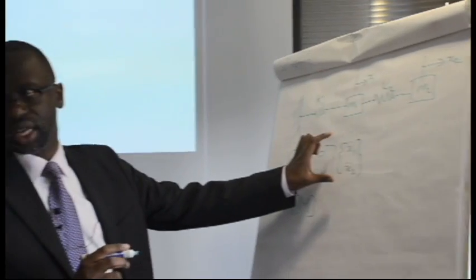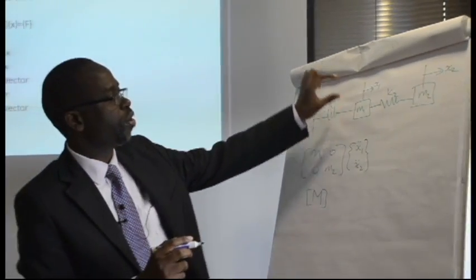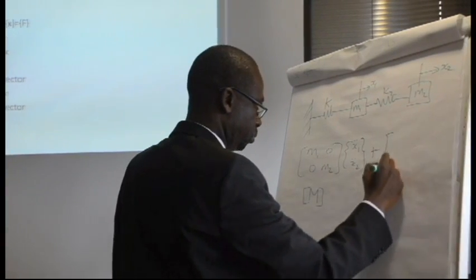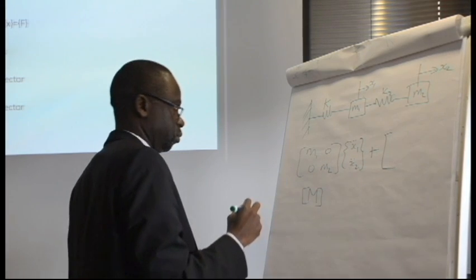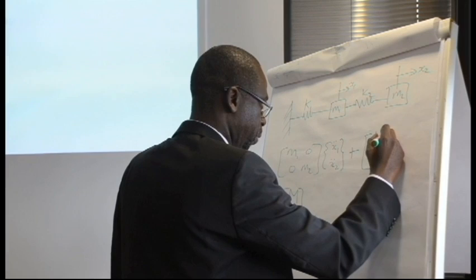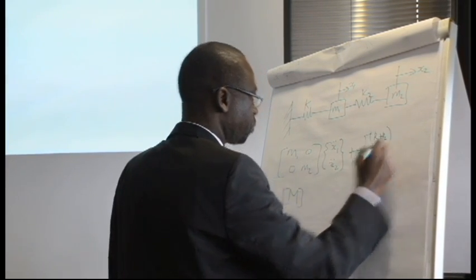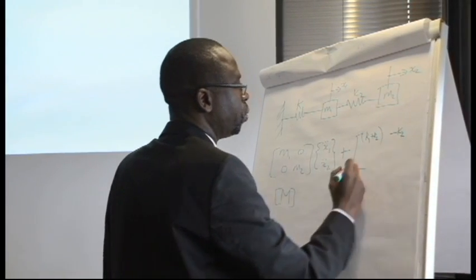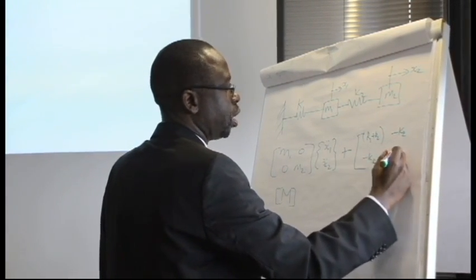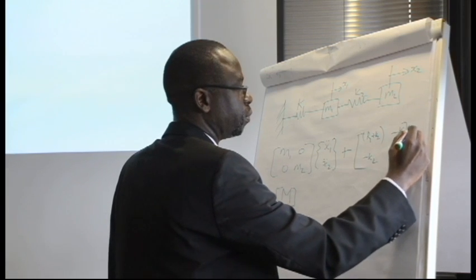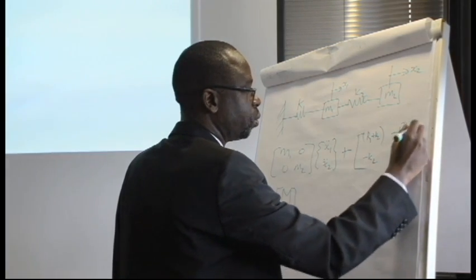This is a vector of acceleration of mass 1 and mass 2, plus K1 plus K2, minus K2, minus K2 and K2, multiplied by x1, x2.